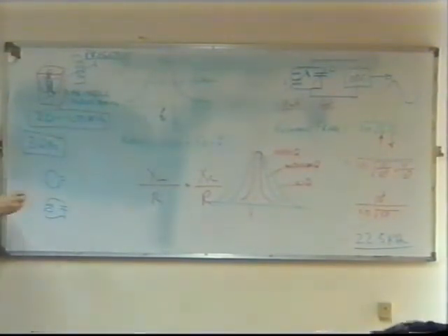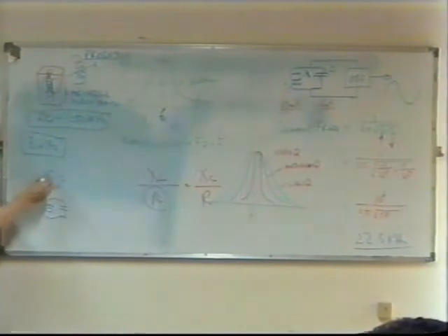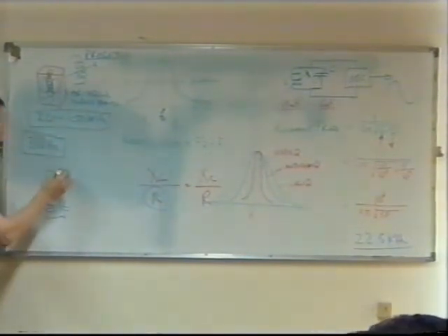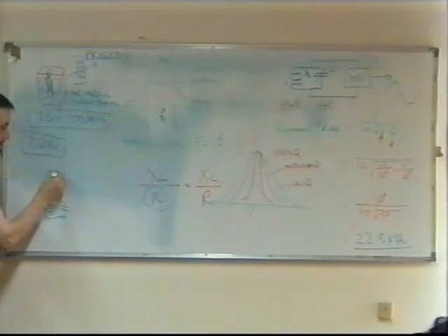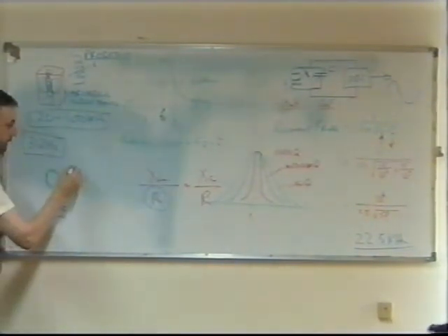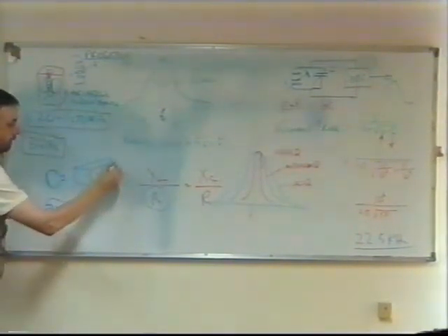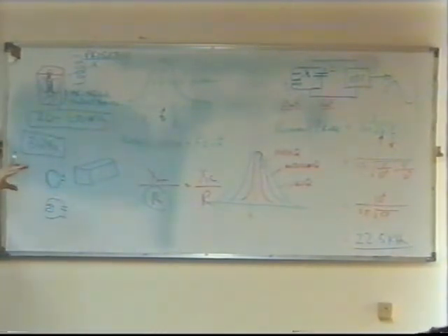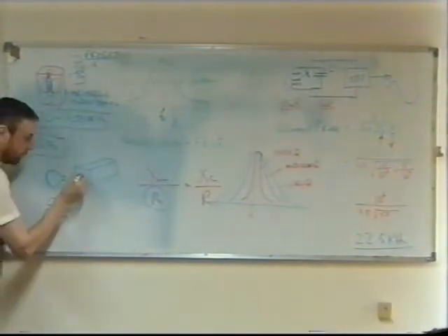Remember, a high Q factor means a very small value of resistance, doesn't it? To make the resistance smaller, I can connect another of these in parallel. So I connect another one like this. You can imagine it just sitting behind it, in parallel with it. Now imagine I connect thousands of those in parallel with one another. Then imagine I make it like this, a big solid block of copper, and I drill a hole in it.